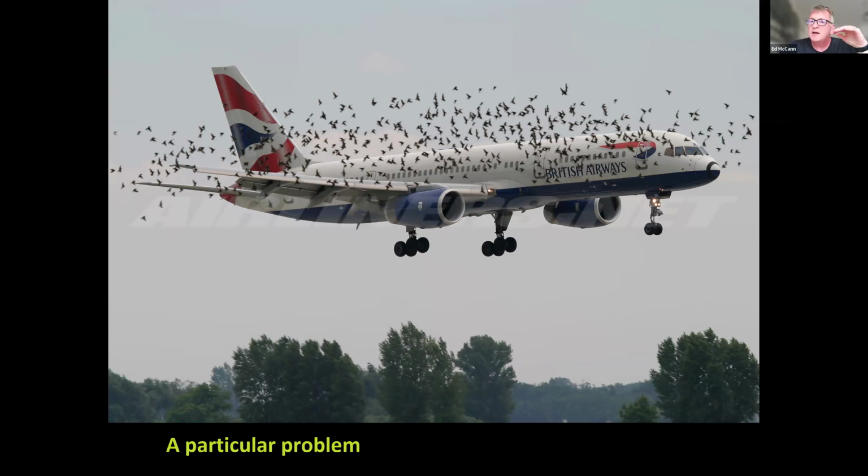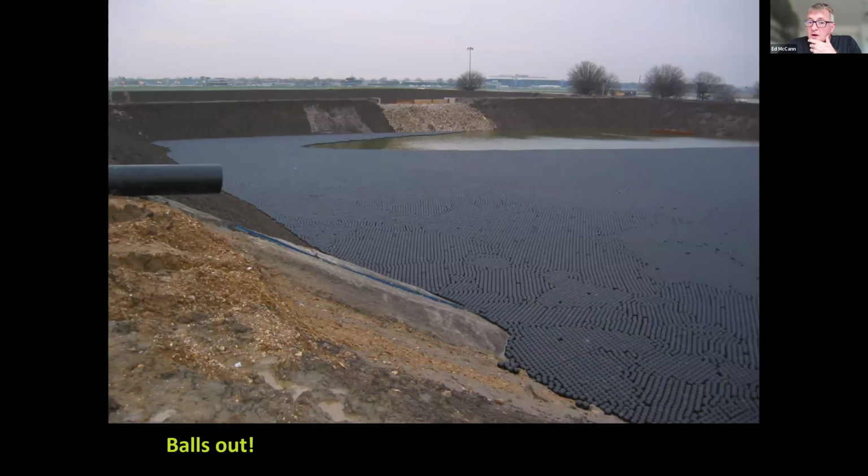And so bird suppression or control is very, very important. At Heathrow, we found that there was this technique that had been developed in the US on tailing dams, which used floating plastic balls. And we decided we were going to use loads of them. We ended up buying millions of the things and putting them in lagoons and across the patch.